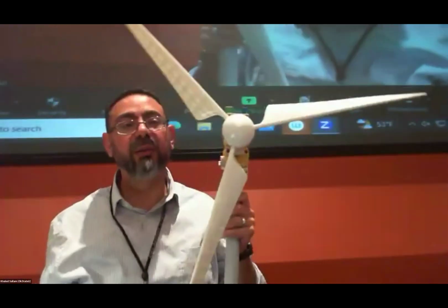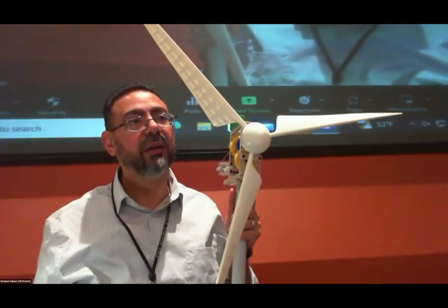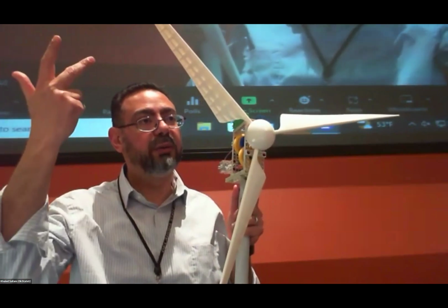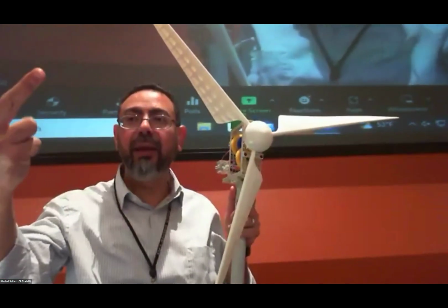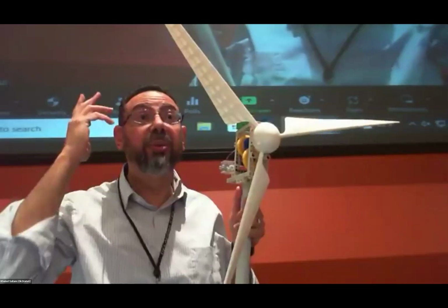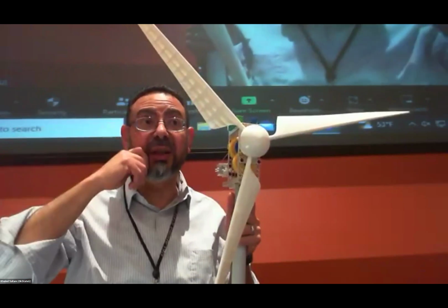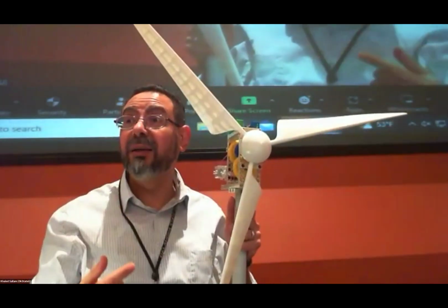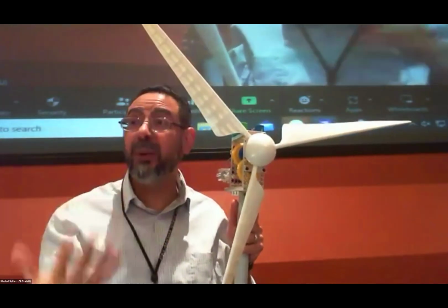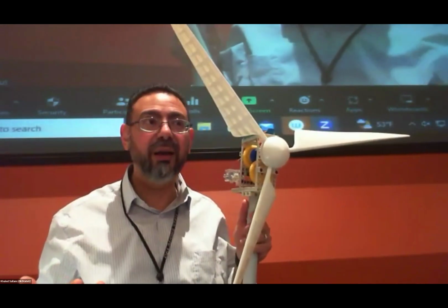Half rho. What's the input power available for that turbine? Half rho A multiplied by V cube, right? So even if the water velocity is small compared to the velocity in the wind, the density, rho air is 1, rho water is 1,000, right?